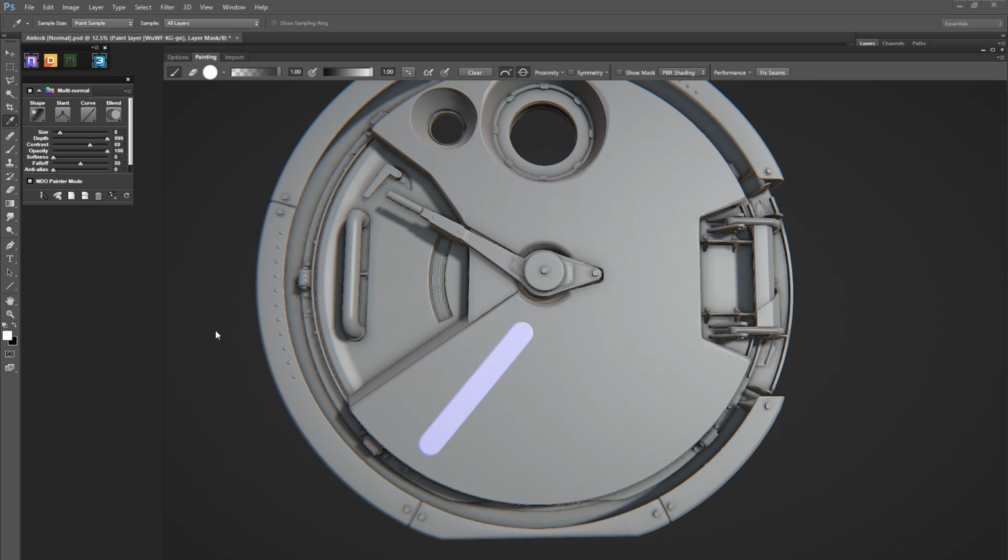There we go. And if you hold N, as in normal, on your keyboard, you can remove the preview of the mask. So in this case, I want to increase the size by quite a lot. So let's try around 30. And change the slant to down so that it goes inwards. All the changes you make here are completely non-destructive and can be changed at any time, even after zipping.